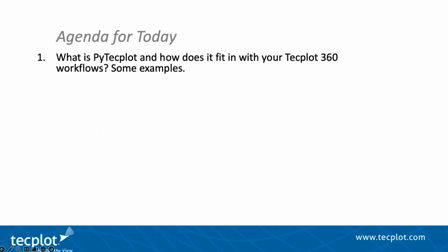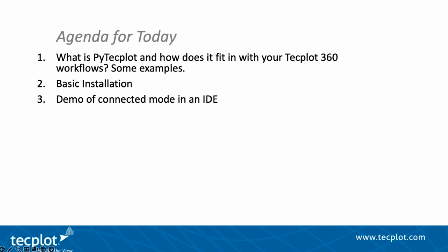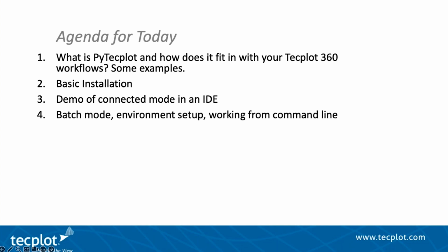All right, so first we'll take a look at what PyTecplot is and how it might fit in with your Tecplot 360 workflows, as well as some examples of that. We'll take a look at the basic installation process, a short demo of connected mode of PyTecplot in an IDE, and then we'll look at batch mode, the other side of PyTecplot, as well as the environment setup necessary for that, working from the command line and what that looks like.